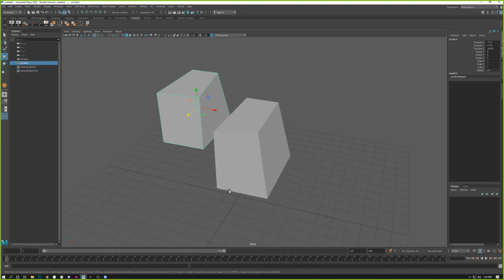Now, you can also enter subcomponent mode on 2 objects at once, in case you were wondering. Same thing. I'm going to hit the F8 key in this case, or come over here and hold down Shift and grab both things. I can select them both before I enter subcomponent mode as well, and I can have more than one thing in subcomponent mode. But whatever is in subcomponent mode is isolated, unless somehow you go add to it.